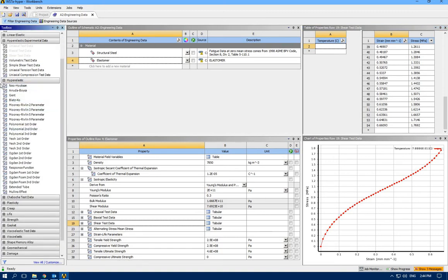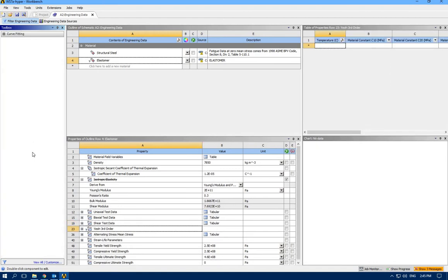As you can see, inside this hyperelastic tab, we have a lot of options and models. I've seen many people using Mooney-Rivlin with different numbers of parameters. I'm going to use the other one, Yeoh third order, and right click, include property.